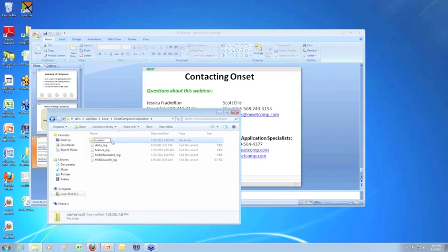There's another question in terms of what type of relative humidity sensor we are using in here. Is it capacitive or resistive? I'm not exactly sure. I can tell you that the sensor is made by a company called Sensirion, and it's an electronically calibrated type sensor. That is something that we can take a look at in further detail.